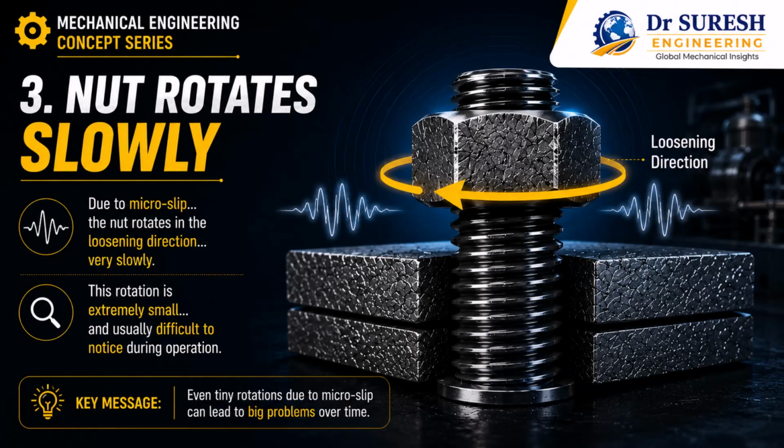Step 3. The nut begins to rotate slowly. Due to continuous microslip, the friction between the threads gradually reduces. As a result, the nut starts rotating in the loosening direction. This movement is extremely slow and almost impossible to notice during normal machine operation.